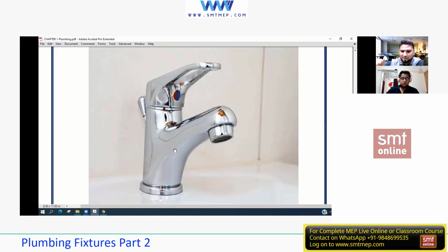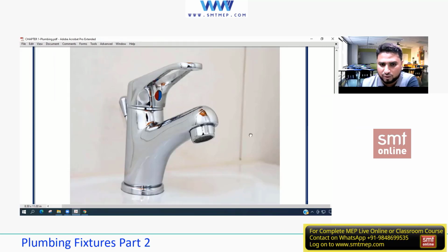Yes or no? If you see the cross-sectional area of an angle valve, you can see a kind of angle inside. Just see this if you have it. When you're installing, try to rotate it, or turn it on and off, and see manually when you have that small device, one angle valve, in hand. So it can adjust. And the best thing about this angle valve is, if I rotate or tilt only a small amount, I'll be getting a huge amount of water, which is more than enough for us.